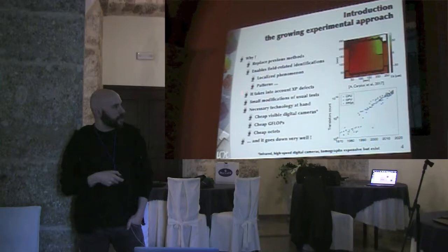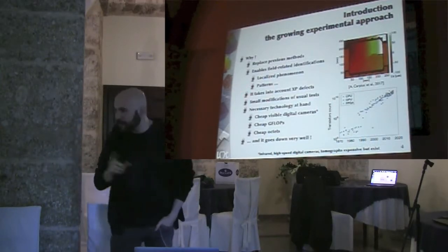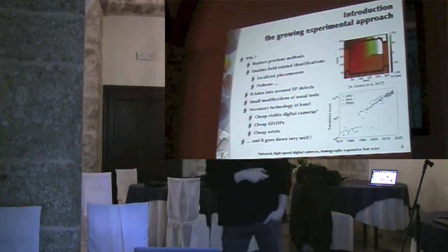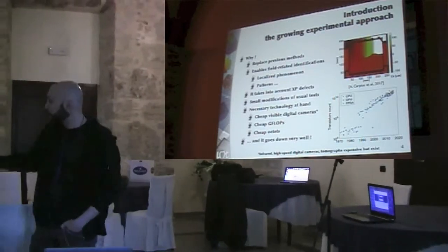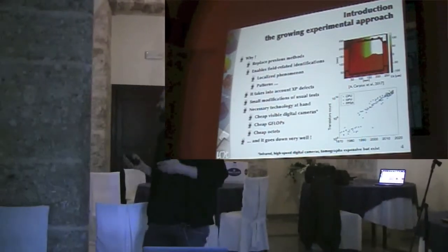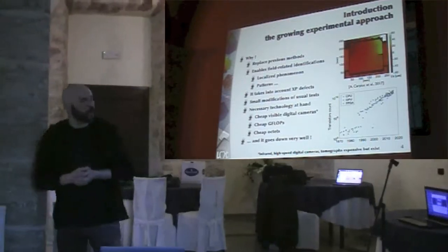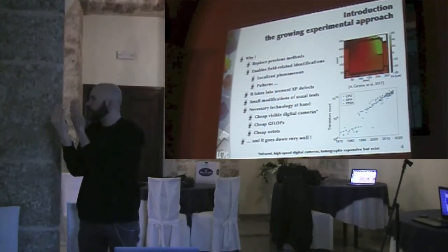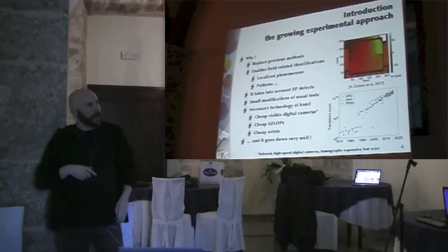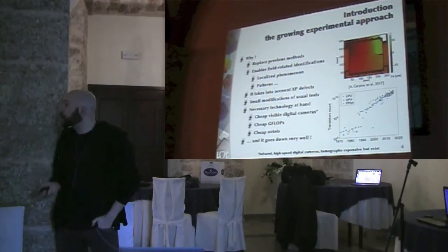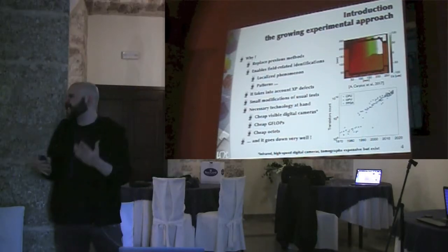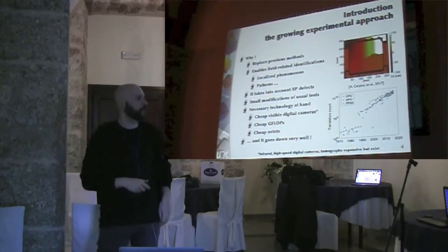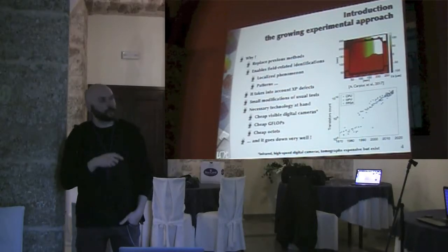It is also interesting because it takes into account different experimental defects, like for example the shape of your specimen. If it's not perfectly the nominal shape you expect, perhaps with the camera you can see that it's a little bit different. It can measure the boundary condition displacement. This could be interesting. You're supposed to be fixed, but well, in fact, the stiffness is not that high, and you've got a small motion. You can measure it with a full field measurement.